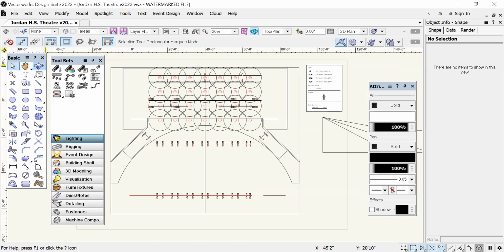The basic tool set is what we'll go through 1 or 2 things on here. The selector tool is your main cursor. The letter X is the shortcut key for that. It will work when you have any tool but the text. If you have text, you'll just keep typing X's, but it's a really good one to learn right away, so you stop drawing rectangles all over the place.